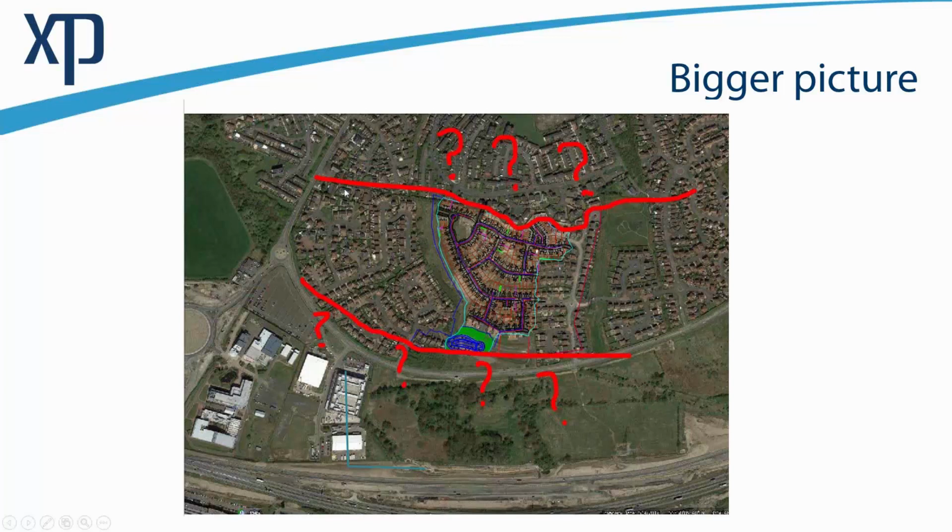image, we will add the DTM, and nowadays there is free LiDAR data available for the whole country. And we can always combine two data sets. You can take a very detailed data set for your existing development and combine it with a bigger LiDAR. So just replace this location on the LiDAR with your information.